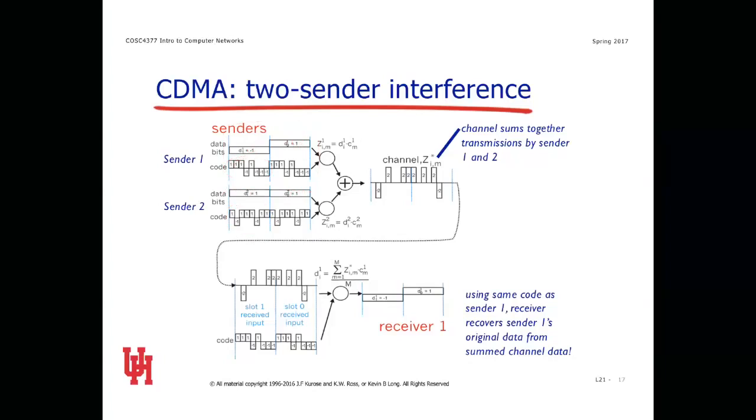So here's what happens. I know that when I had my first signal times a -1, if this was my chipping sequence, I'm going to invert it, right? We know that. So that's what I'm going to do. I'm going to turn this into the following: -1, -1, -1, 1, because this one gets inverted, and then another -1, and then 3 ones, right? So far, so good?